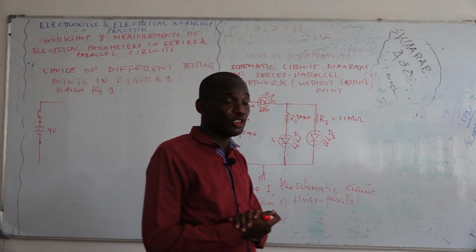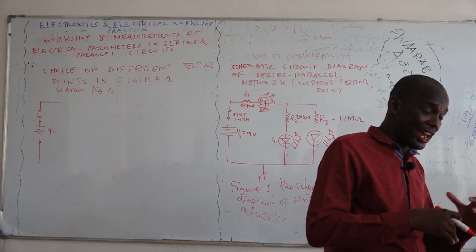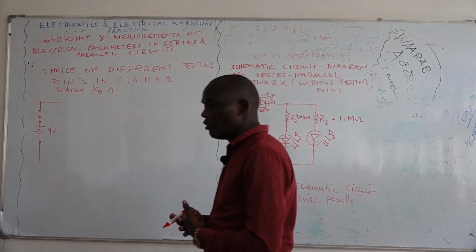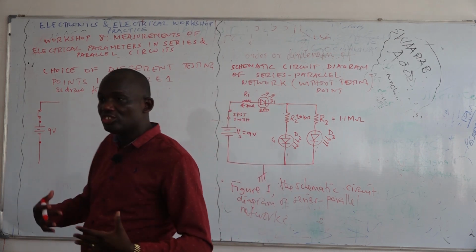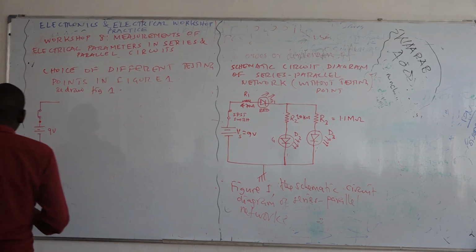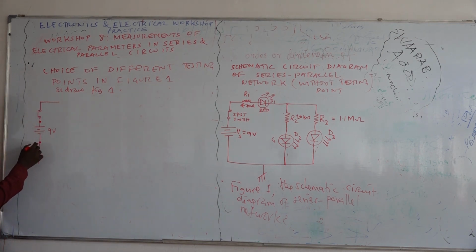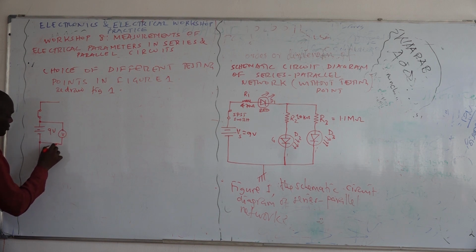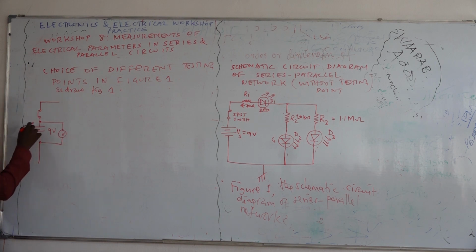Especially for the hardware implementation, because when you use the battery to power your circuit, the voltage actually decreases. So the first testing point is this one, where our interest is not to measure current, our interest is to measure voltage. So we may call this our testing point A. I said stop writing, look on the blackboard.